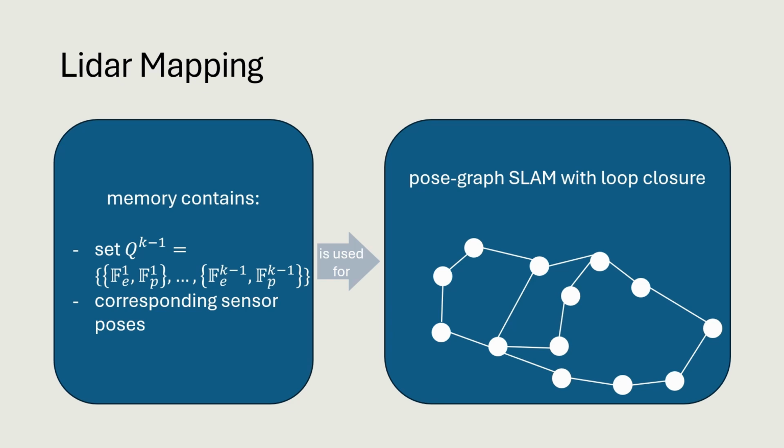The pre-aligned pose of the new measurement is added to the pose graph. For the edges or constraints between the recently stored nodes, for which zero drift can be assumed because they represent the sensor poses of the lastly recorded sweeps and the one we want to add for the newly captured data, we utilize the transformations obtained from the Levenberg-Marquardt optimization as before.